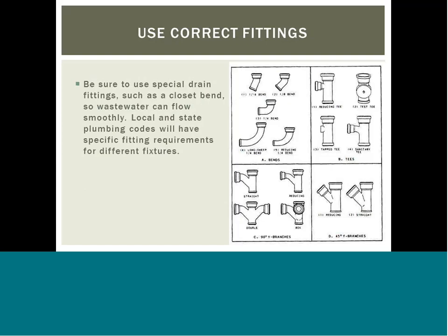Be sure to use special drain fittings, such as a closet bend, so wastewater can flow smoothly. Local and state plumbing codes will have specific fitting requirements for different fixtures.